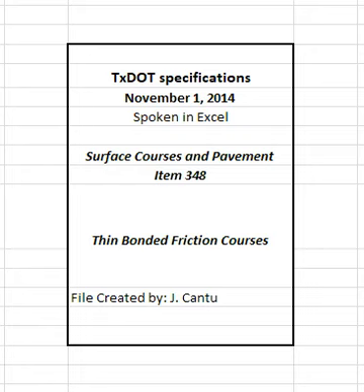Determine the moisture content, if requested, by oven drying in accordance with TEX 212F, Part 2, and verify that the mixture contains no more than 0.2% of moisture by weight. Obtain the sample immediately after discharging the mixture into the truck, and perform the test promptly.